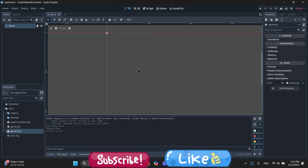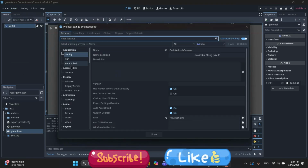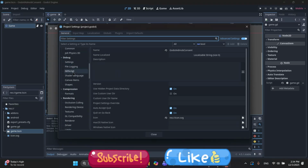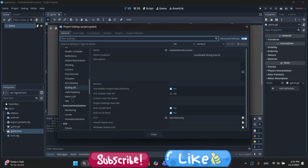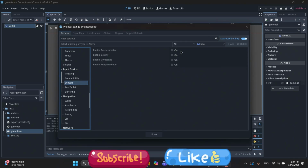To make use of the accelerometer, first of all we need to go to Project, then Project Settings, and find the Input Devices menu. In the input devices there is a Sensors tab. Click there, and in the sensors we are going to enable the accelerometer.